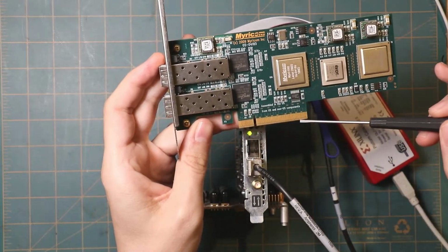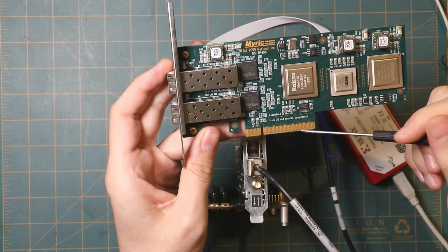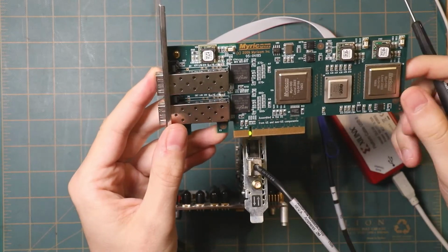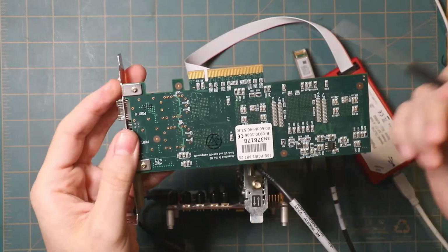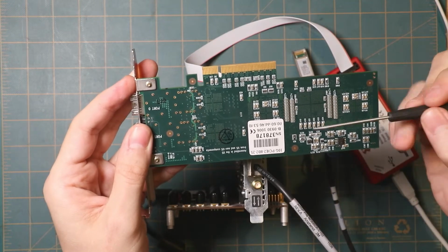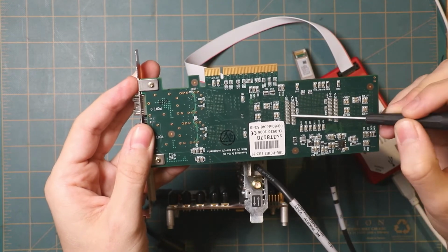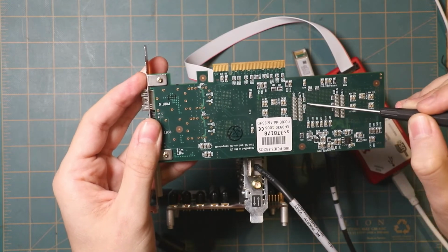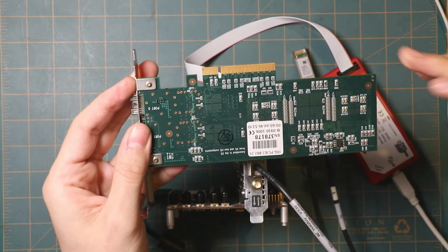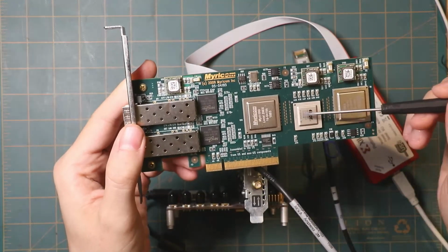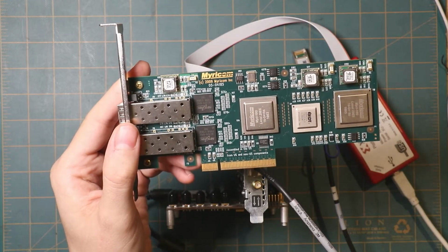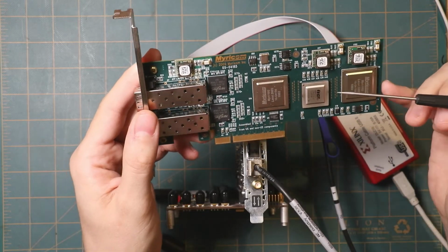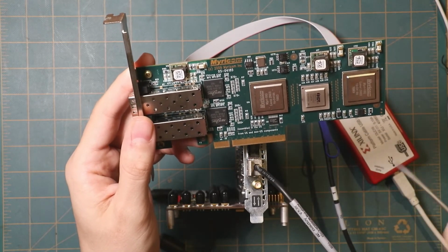We've got PCI Express. I believe this is a Gen 2 x8 interface. And then that's connected to this PCIe switch chip. And then between the switch chip and the 2 NIC chips, there's a whole line of capacitors here, right? There's 2 lines, there's 8 little pairs here and 8 pairs there. So that indicates that we have 8 lanes of PCI Express between each of these chips, right? And I believe that's 8 lanes of PCIe Gen 1, but I would need to check in lspci. I haven't plugged one of these NICs in a while. I can't remember exactly what it is.